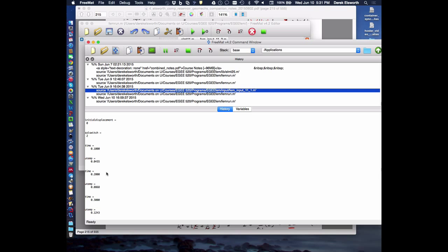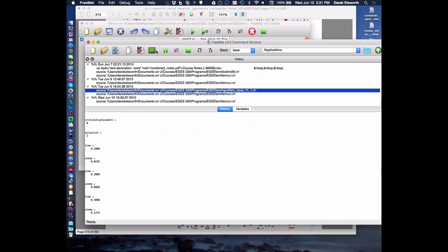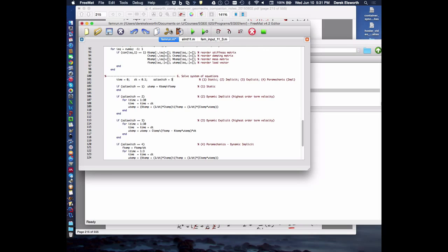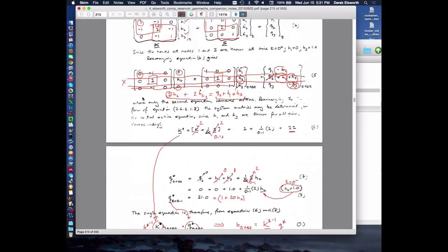Now if we use a larger time step. We used a time step of 1 and it was perfectly stable before, and that was fine. It gave a different result. Let's try the same time step with this explicit method, which is only conditionally stable. So we clear this out, we run it, and we see what we get. The first time step is 0.05, and it should be of that order. Actually, that's exactly the result we got, right?